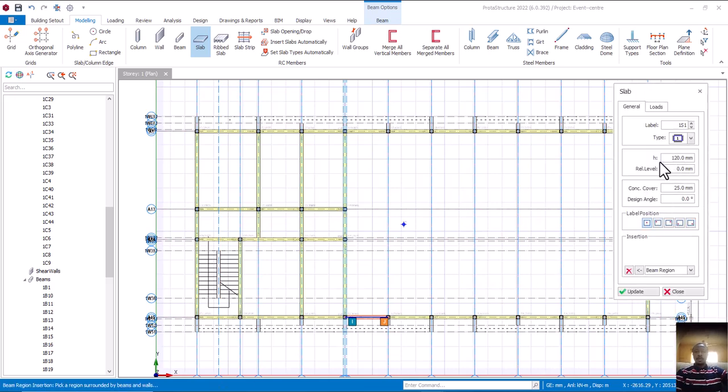Okay, here we are. So you can now see our beam depth. I'm using type 1. Why? Because the condition of my slab is that we are having a support at all ends. For this side, this side, this side, this side, we're having support. That's why we're having type 1. We have different types of slab here. Can you see them? In my own case, I'm using type 1. I will now come to this place. The depth of my slab is 150. So that is fine.